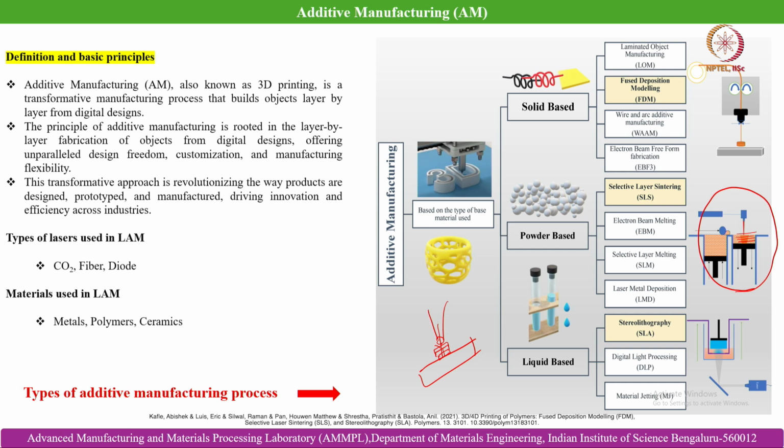and yes, one can argue that in DED the material wastage is much lesser compared to laser powder bed fusion. However, in case of DED the cooling rate is much lesser than in case of LPBF, and we often end up getting a coarse microstructure in directed energy deposition rather than what we achieve in laser powder bed fusion.